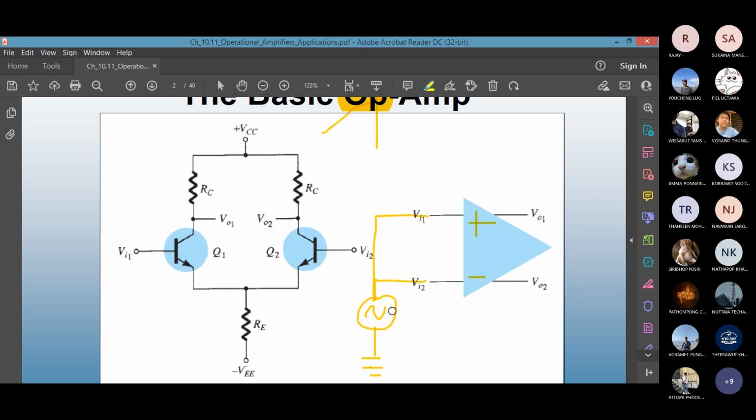If you put the common mode input, you see a plus, and the same peak is multiplied by minus, plus minus gets cancelled out. This does not happen with differential mode, because for the differential, one side is plus, another one is minus, so minus with minus becomes plus. Ideally, I said for the common mode input, the output should be 0. But in real life, there's a little bit of signal coming out.